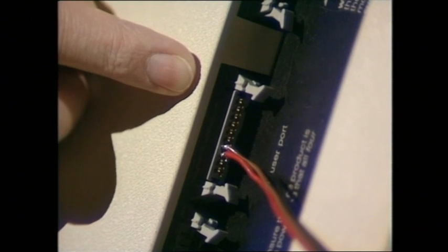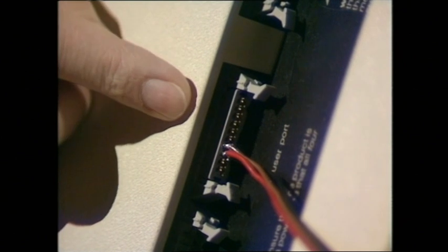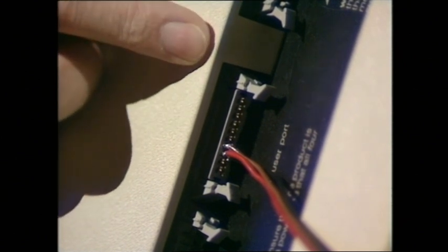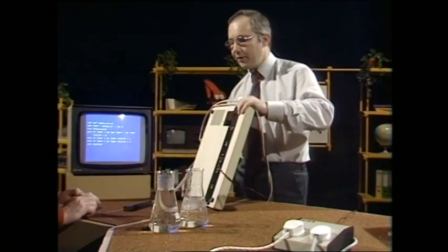One is an earth connection, and the other 2 contain the signal connections to say that the fan or the heater should be switched on. And there are in fact 6 other unused connections corresponding to the 6 bits in the byte that we weren't using. Let's follow down that wire and have a look at the control box.